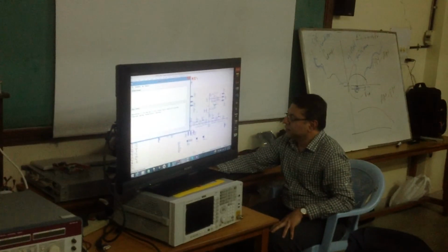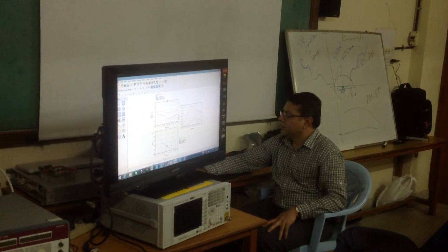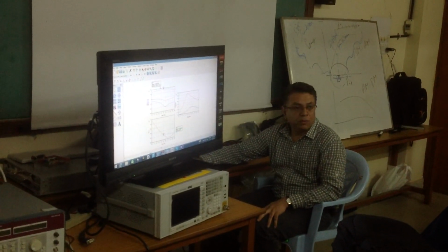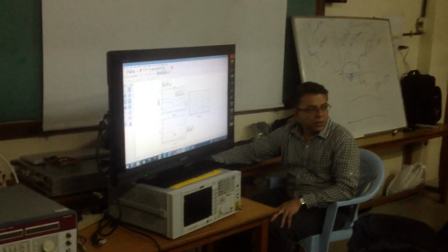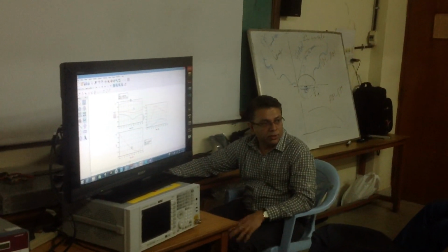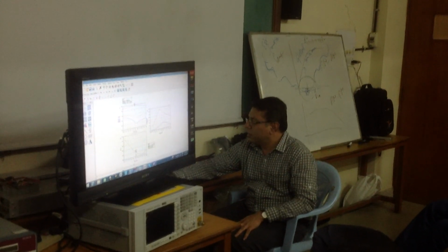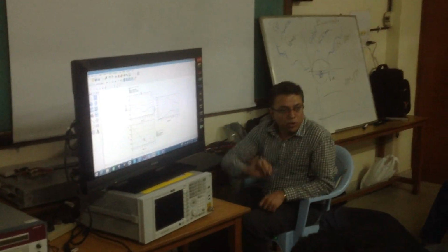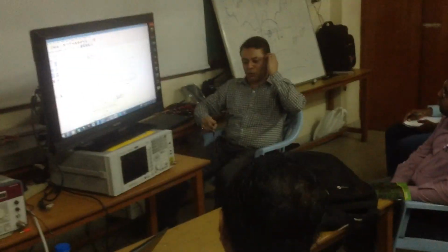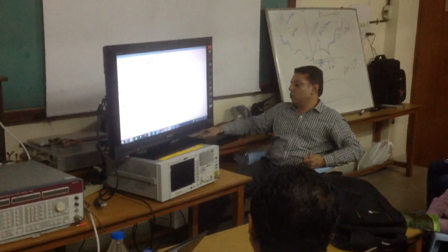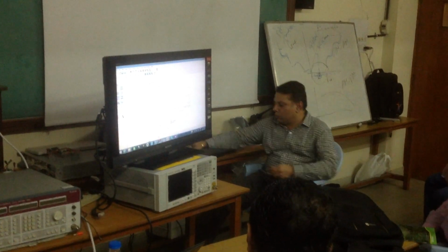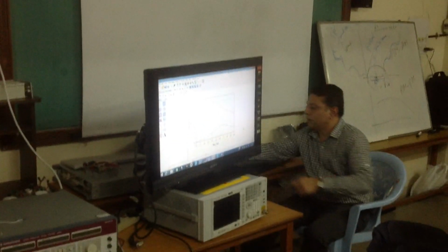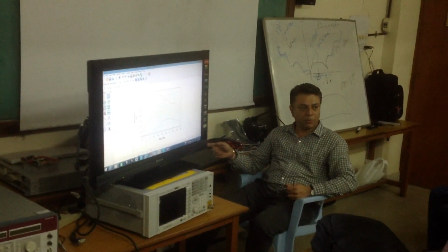So I run it once again. Now you see here, how much is my noise figure? 0.7. Everything else is the same. 17.8 dB. Earlier it was 2.2. And this is my stability factor. Instead of K, here mu and mu dash are used. It's again the same as K only. Everyone knows about those things. As long as mu is greater than 1, it's similar to K only. So you can look into this also for the stability. Because of the resistor, there is stability now, and it is clear. There is no problem in the stability part also.